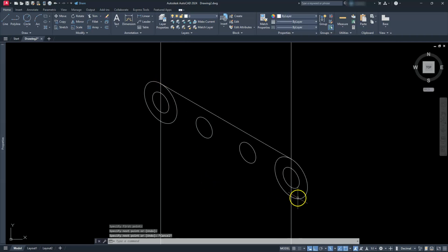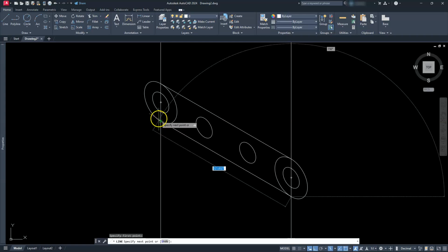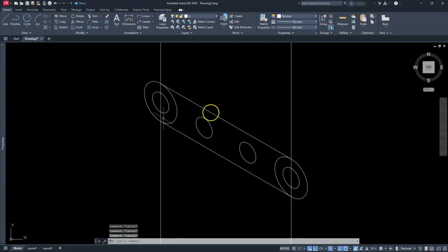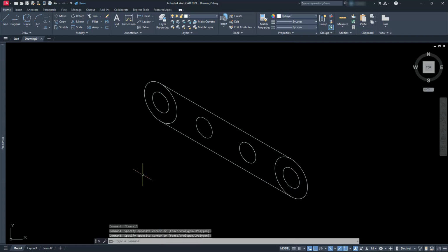Okay, likewise here, I'll draw a line from this intersection going straight across to that intersection. Okay, let's go ahead and escape out of that, delete my two vertical lines here, and then trim in between them. So I'll go ahead and use the type in commands here. So trim, go ahead and trim that portion off.